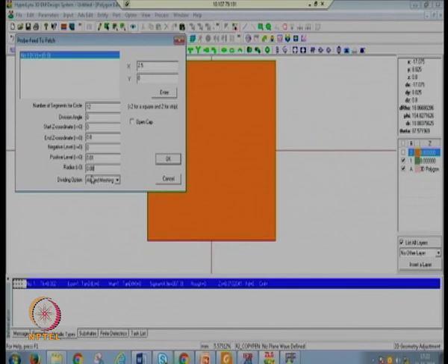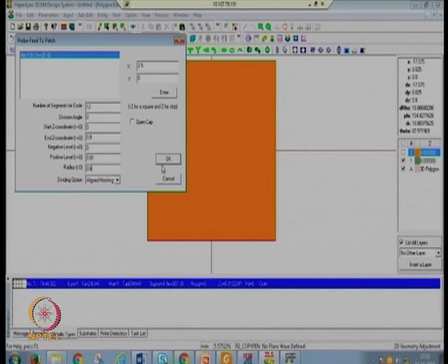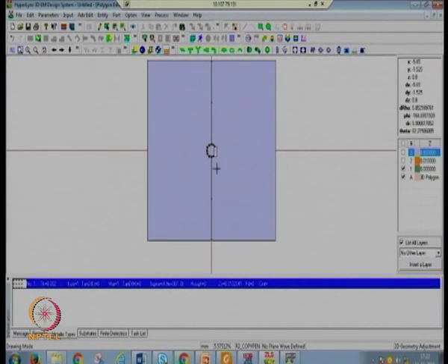Here we are providing a coaxial feed. So in this case, since we are dealing with C band, and this particular antenna is at 5.8 gigahertz, we will use SMA type of connector, and the radius of SMA type of connector is 0.6 mm. So let us give it 0.6 mm, put it, sorry, I could not enable this particular thing.